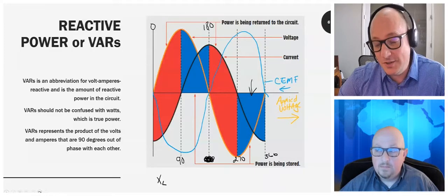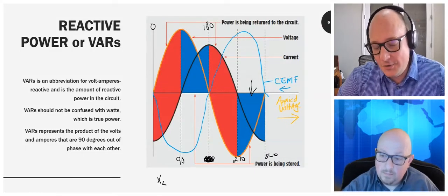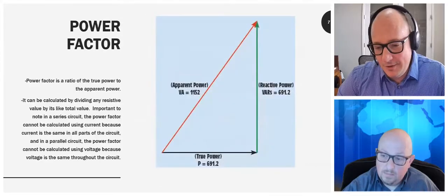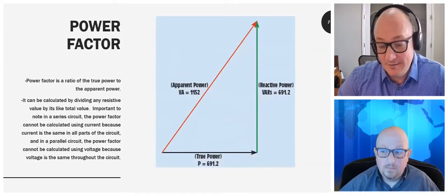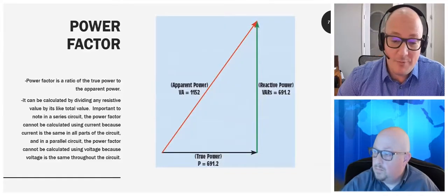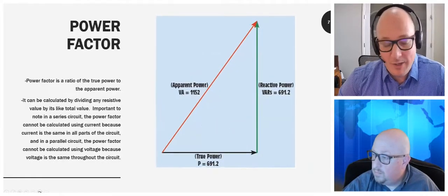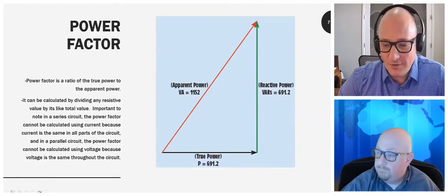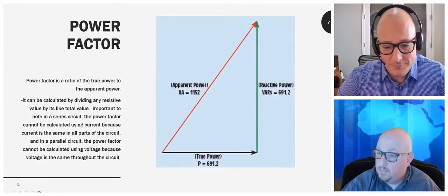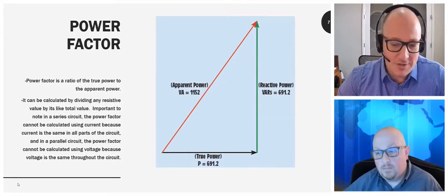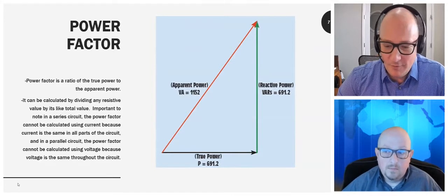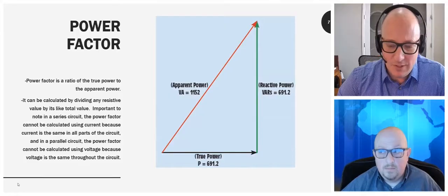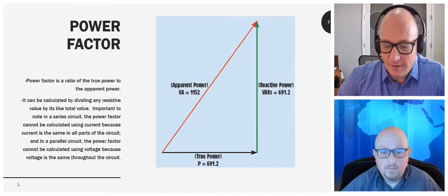So even the utility encourages you to have better power factors in your commercial facilities. You're not paying for power in kilowatt hours, you're paying in kVA hours. So you're encouraged to have a better power factor. It decreases your bill. So the end user decreases the bill, but everyone's happy because we don't have to put in as much power either.